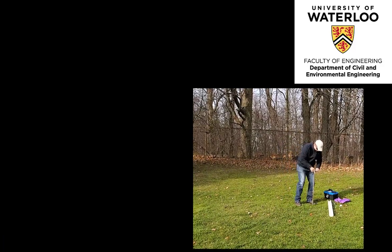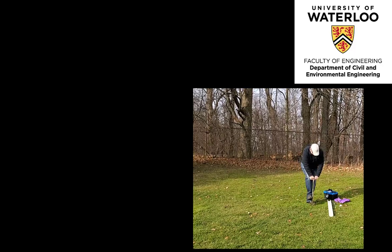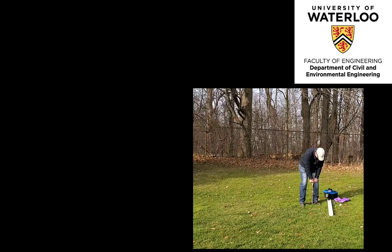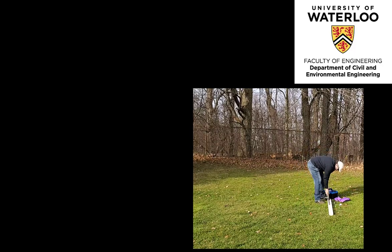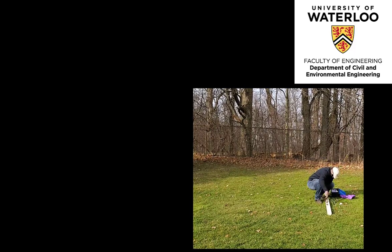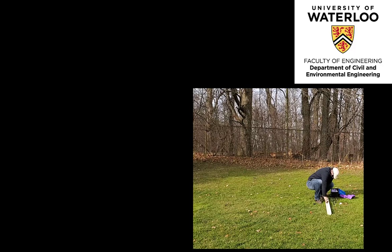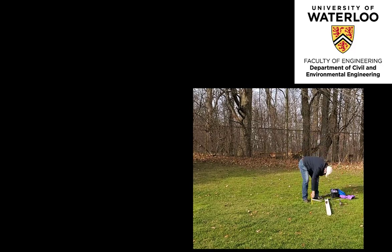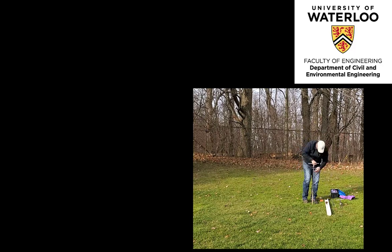A small diameter shallow core auger is advanced into the soil. The recovered sample is extruded and the core advancement depth measured directly in the hole, in this case referred to as the travel distance, and the auger advancement was 25 centimeters into the subsurface.